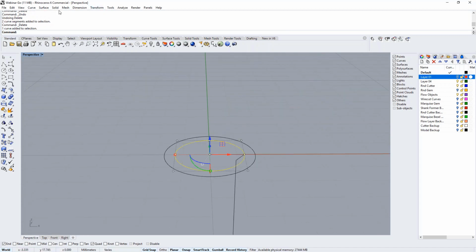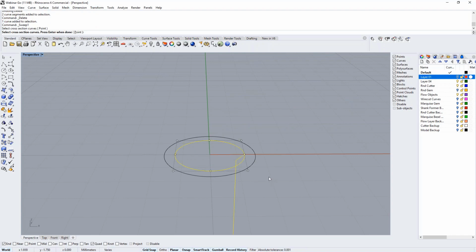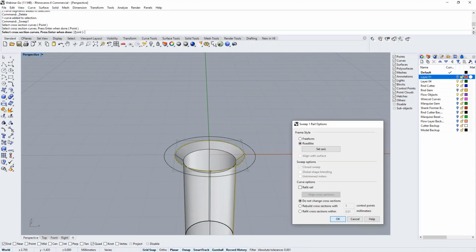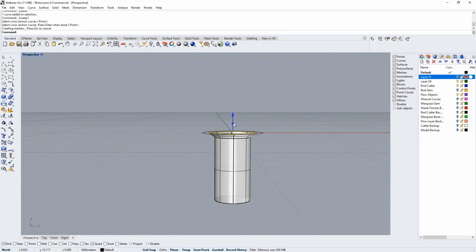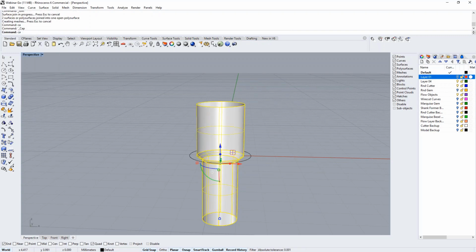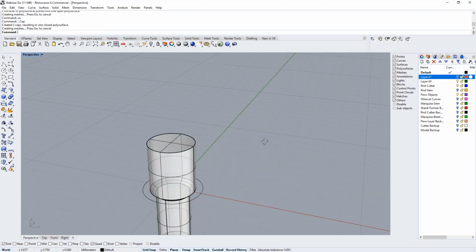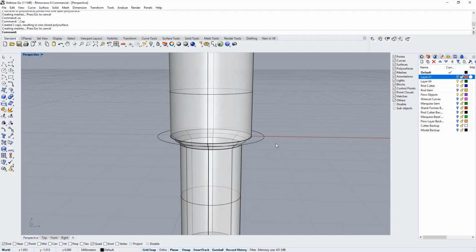Okay, so this surface sweep one rail, this is a cross section, boom, there. And then we take this line, sorry for the confusion, and we extrude it. And then we join these two surfaces, Control J, and we cap them. Okay, that's our cutter. I guess in my mind, I was creating a bezel.